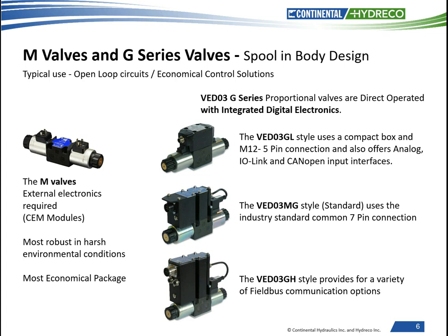The disadvantages of an OBE: the valve and controls are one package, not individual components. If the valve gets worn out or contaminants damage the valve, you must replace both the valve and the electronics. If the electronics get damaged from a power surge or a short, you must replace both the electronics and valve. This is very costly at times from the user standpoint. Reprogramming also takes a little bit of work and a programming box. Note, if you do reprogram onboard valves, you can lose the valve-to-valve interchangeability.